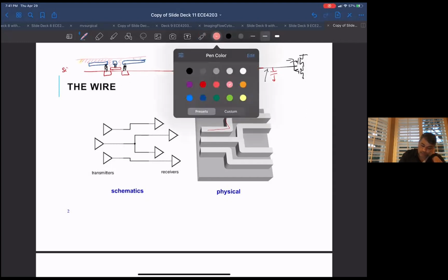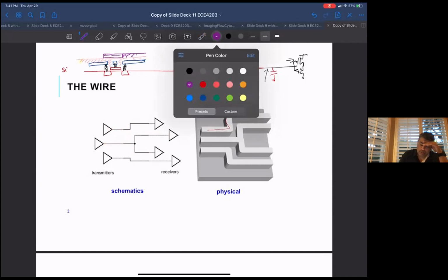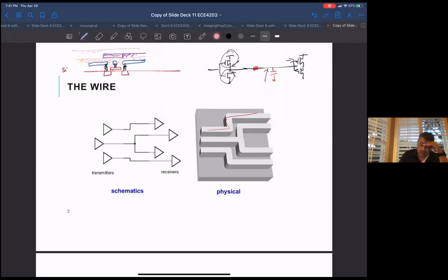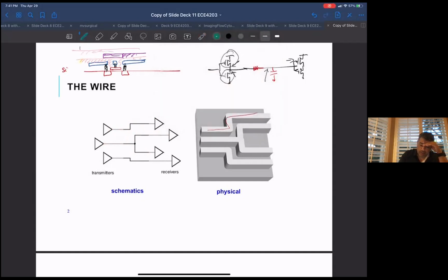Okay, and then you can put in another layer of metal, like metal 2, for another set of connections, because you need to connect different signals to each other, and you need to bring power and ground to all your circuits. So you basically build layer after layer. Next, you put in another layer of dielectric and another metal layer. Okay, and you build up your connections that way.